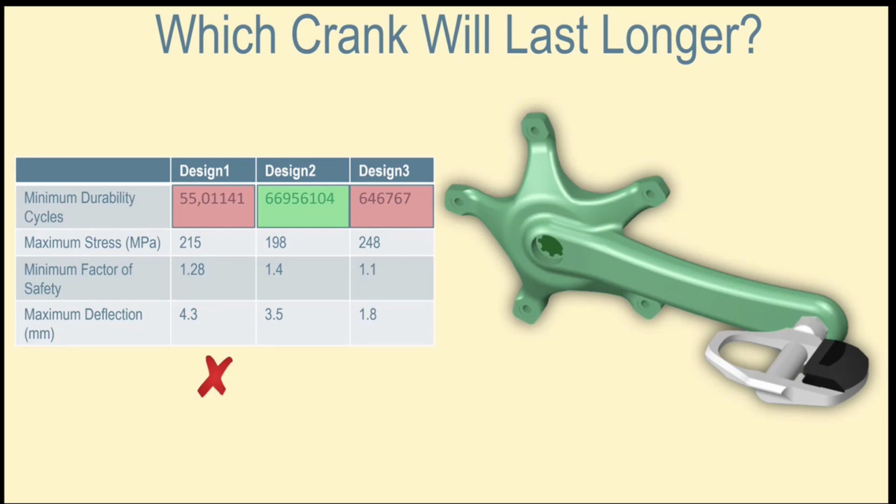And of course the calculated stress, that is 215 megapascal, is also not taken into consideration, because we are considering the life of the component. So design 3 is also failed, and ultimately design 2 is passed. And you can see what the design tool is looking like. Okay, so you can see what has actually happened. It is completely how you add material and remove material, how you make the design.